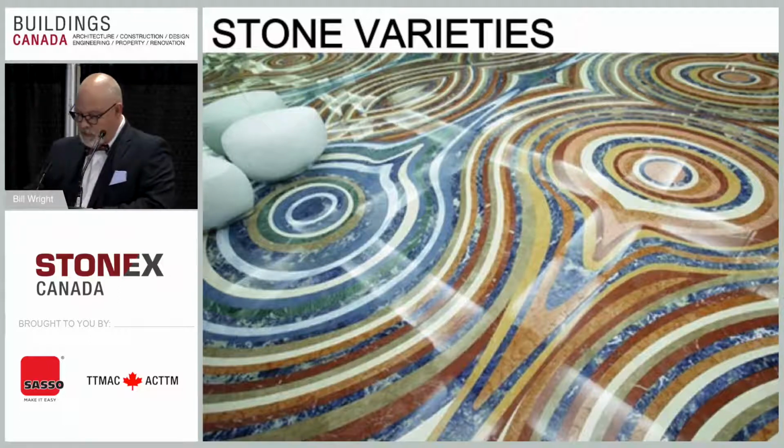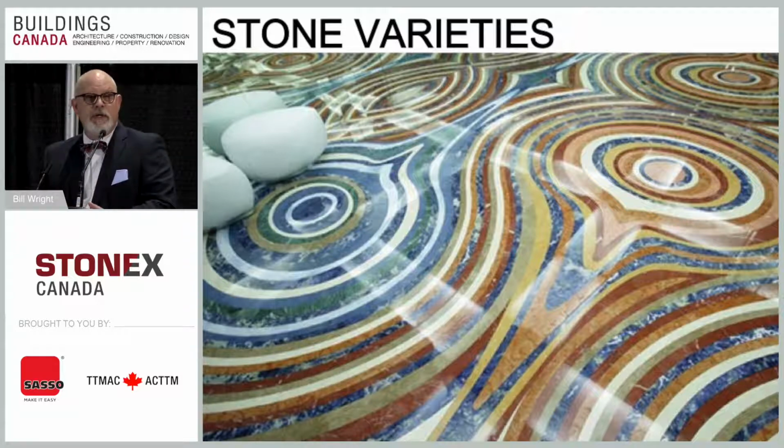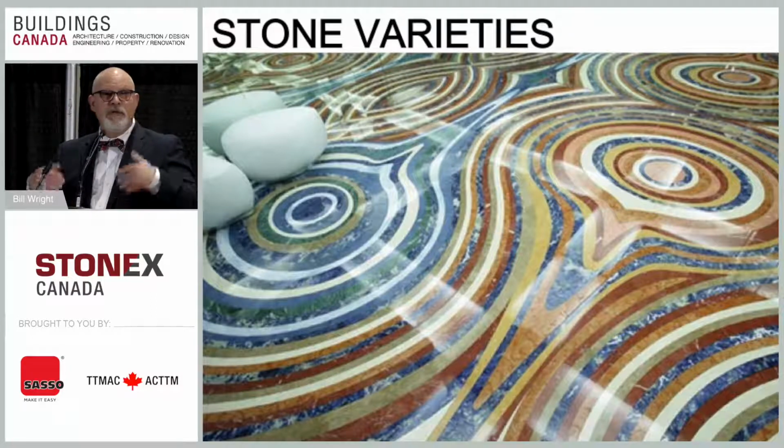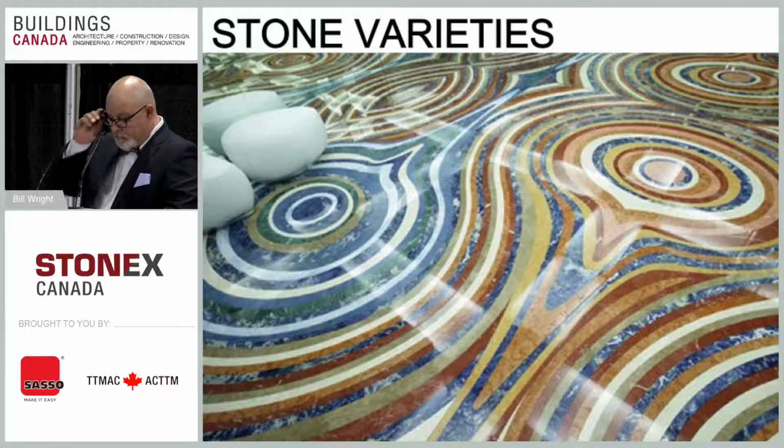There's lots of different stone varieties out there. Lots of different textures, more and more textures all the time, like we were talking about. When we get into stones on walls and large format tiles, we prefer cement type or cement board types of materials than drywall. We want things that are nice and stiff. We've had issues where they've used traditional gypsum drywall for big, large format tiles, and the walls are just too flimsy. Things either crack or they break. So when we get into these bigger, larger materials, we want cement or cement board types of assemblies to install tile or stone onto. Generally, you're looking somewhere in the neighborhood of a deflection of about an L over 720, a very good stiff substrate. Okay.